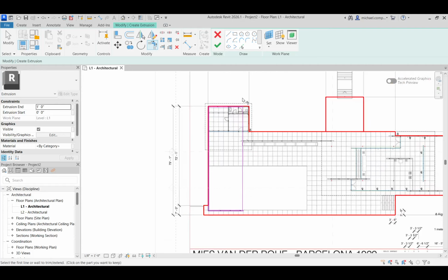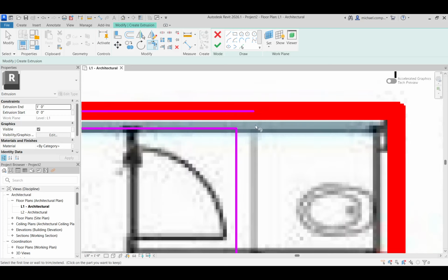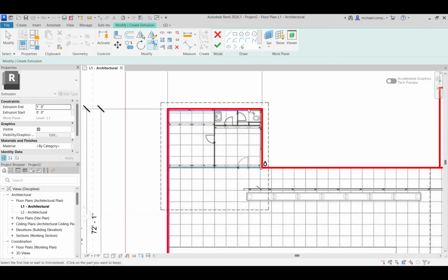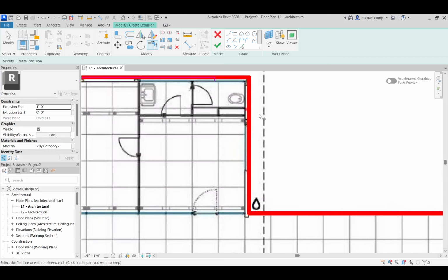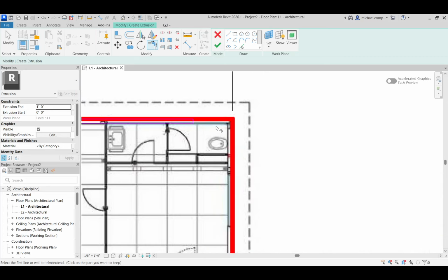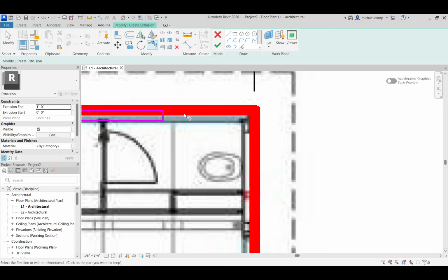We're going to go to the other end and do a very similar process. So we're going to choose the line we want to trim extend to, choose that line, and then just clean it up one more step. And what you'll now see is I have a big U shape. I find that to be a really easy way of manipulating line work instead of drawing point to point to point to point, but I'm going to show you that here too in a second.